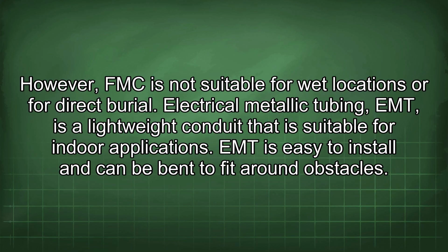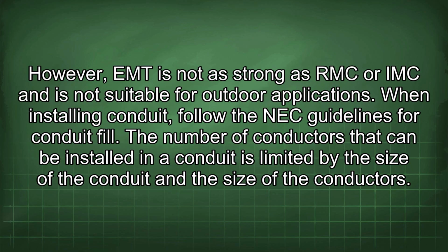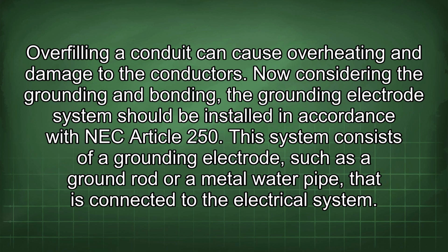Electrical metallic tubing (EMT) is a lightweight conduit that is suitable for indoor applications. EMT is easy to install and can be bent to fit around obstacles. However, EMT is not as strong as RMC or IMC and is not suitable for outdoor applications. When installing conduit, follow the NEC guidelines for conduit fill. The number of conductors that can be installed in a conduit is limited by the size of the conduit and the size of the conductors. Overfilling a conduit can cause overheating and damage to the conductors.